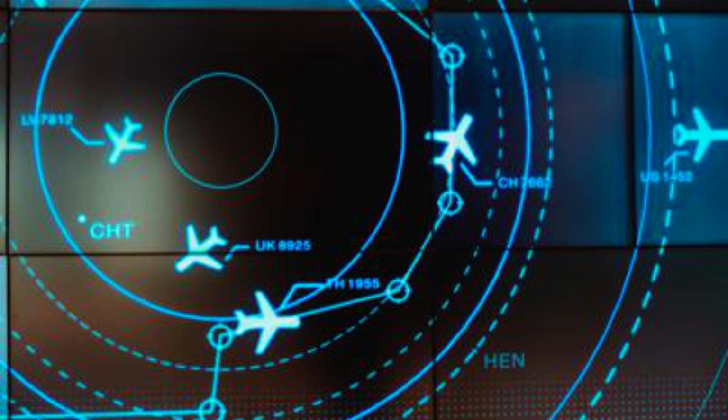The controller is not required to provide terrain and obstacle clearance just because ATC has radar contact with your aircraft. It remains your responsibility until the controller begins to provide navigational guidance in the form of radar vectors. Once radar vectors are given, you are expected to promptly comply with headings and altitudes as assigned. Question any assigned heading if you believe it to be incorrect or if it would cause a violation of a regulation, then advise ATC immediately and obtain a revised clearance.